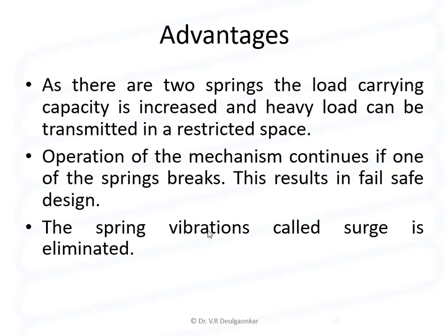Now the advantages of such a combination are that we can design a spring with increased load carrying capacity in a restricted space. Operation of the mechanism continues if sometimes one of the springs fails or breaks. This actually results in a fail-safe design.